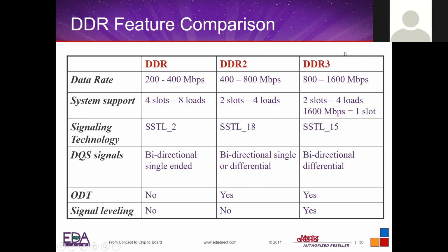And because of all these impedance and switching and all these things, they added this on-die termination capability. That opens up a slew of issues, problems, things that actually challenges, right? So there are many ODT settings that I can set. Which one is the best for me? Number one. Number two, I used to do my trace impedance at 50 ohm. Is that the optimum trace impedance, or should it be 42, 43 ohm? Why do I need to choose that? Because of the ODTs.